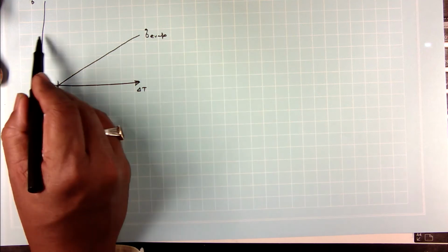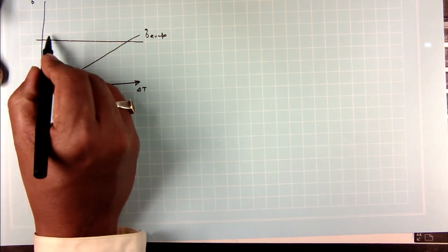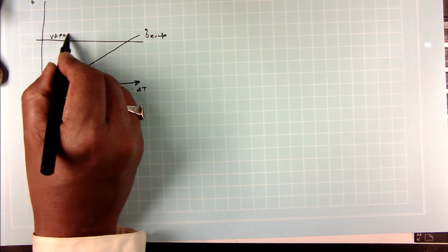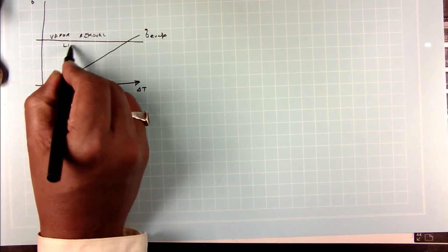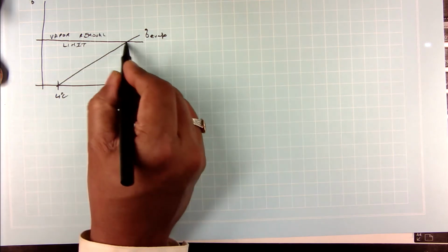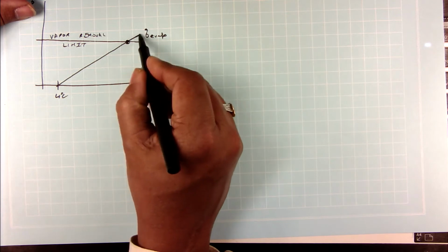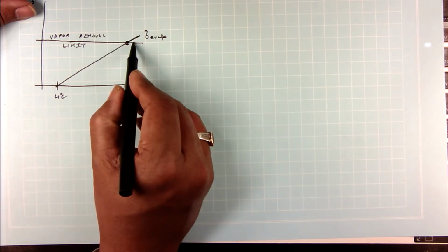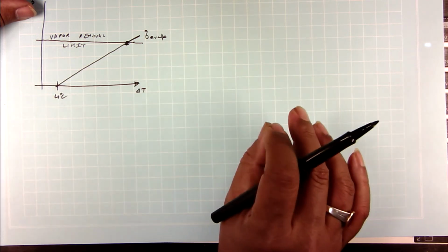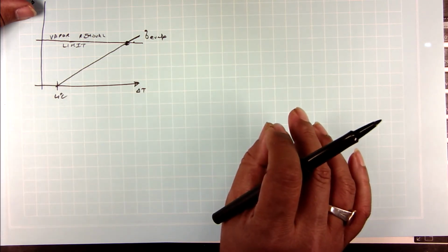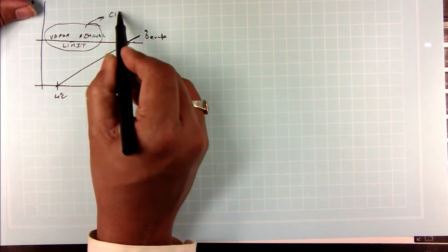And the rate at which you can take vapor bubbles out of your system is where your critical heat flux comes in, because if you produce more vapor than your vapor removal limit, what happens? It starts forming the blanket, isn't it? So this is the limiting factor that determines your CHF.